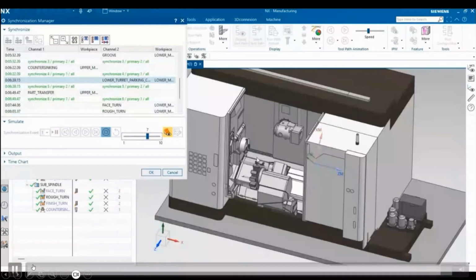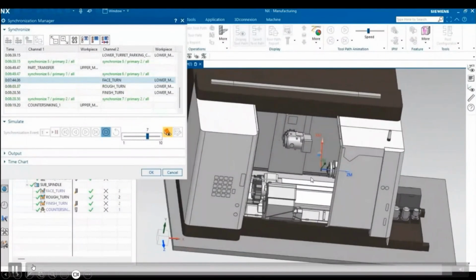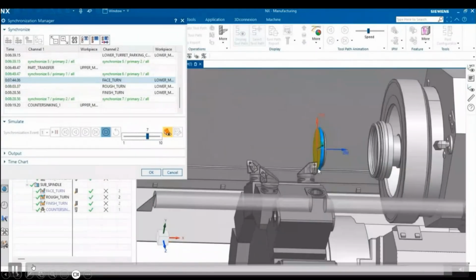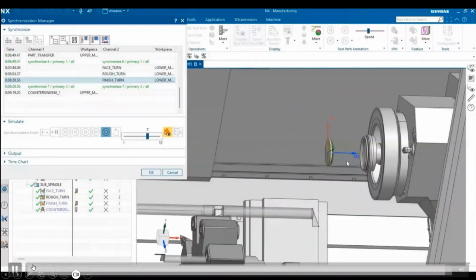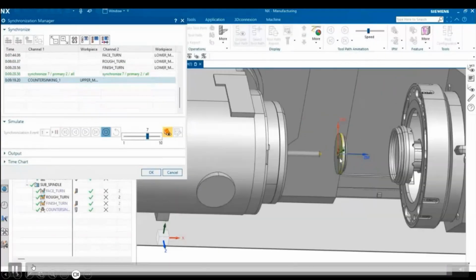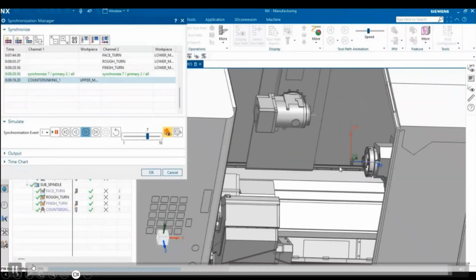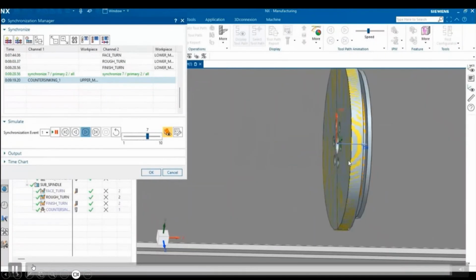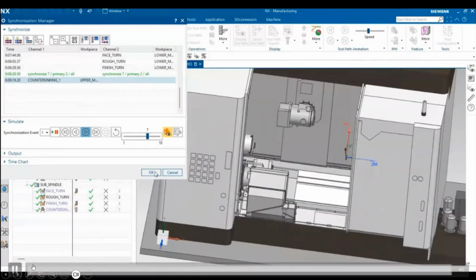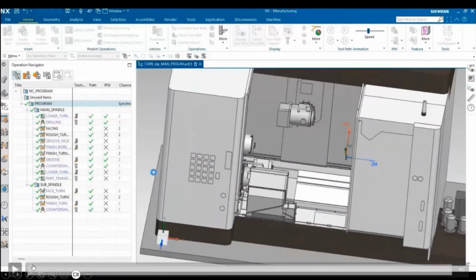It's showing gouge and collision checks between your tool, your part, your IPW, devices, tooling blocks, machine components, all these things. Displaying machine times and machine status analysis. This supports changeable devices like heads and tables, fixtures, vices, etc. Shows clamping, reposition or transferring the parts, your IPW, shows limit violations, and you can display the current locations of all axes.